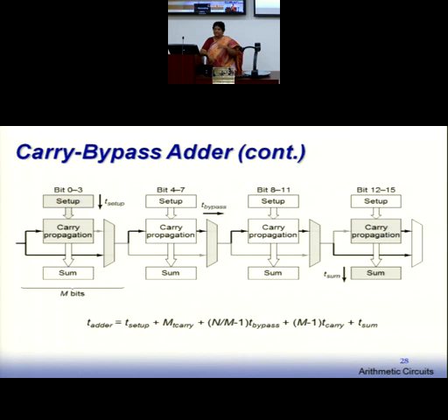But then, as you said, we can find an optimum value. For radix 4, you are having a block of 4. You are combining 4 bit positions together, computing G04 or P04, because P04 is becoming your output carry. So in this situation, what if I choose a block of 3? You are changing the radix. Radix 3, radix 4: compute a block of 6 bits, or a 4 bit block, or a 2 bit block at a time.